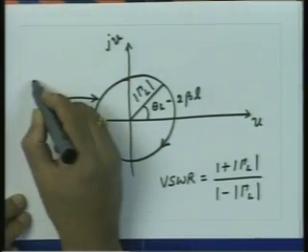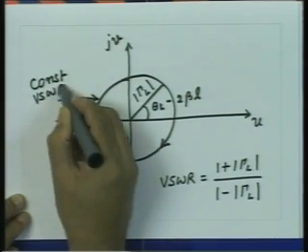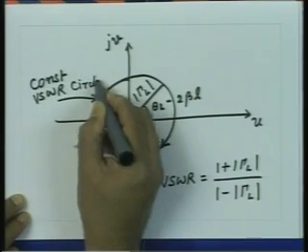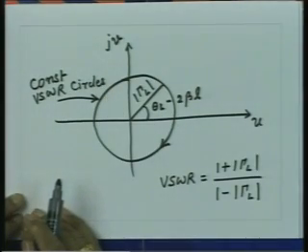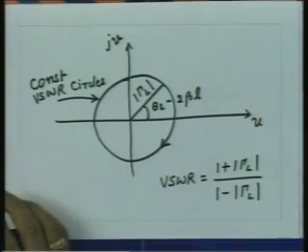These circles you have to draw whenever we solve the transmission line problem using the Smith chart. The Smith chart readily gives you the set of constant resistance and constant reactance circles, and while solving the problem we have to draw the constant VSWR circle on the Smith chart and then do the transmission line calculations.